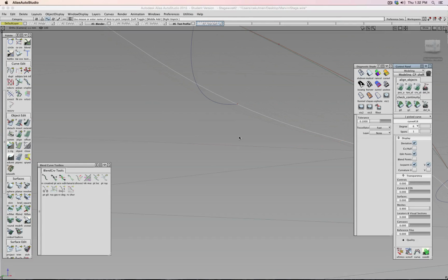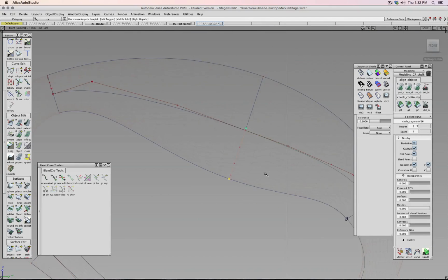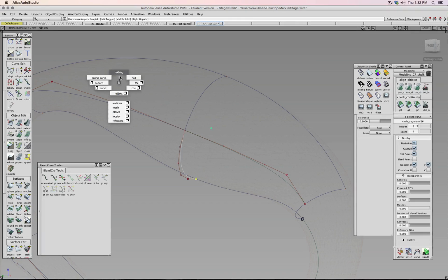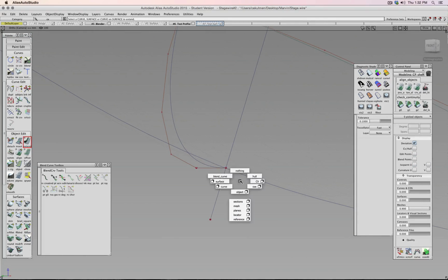I have to turn off those CVs there, curve, show me my CVs, and I have to make sure those lines are on that curve anymore. But let me show you again the small trick to make sure that I do not deform my curve too much. So click on here, click on there. So this is basically one end to the other end. I'm going to extend this line just again a little bit. Then this CV, I move really far away, and then simply I snap to that intersection.